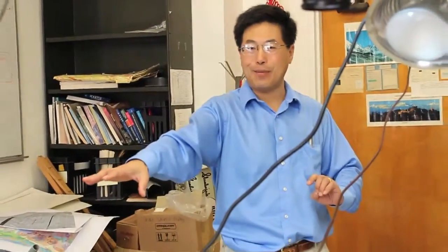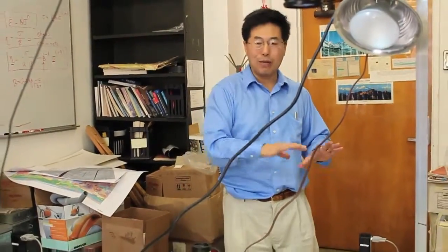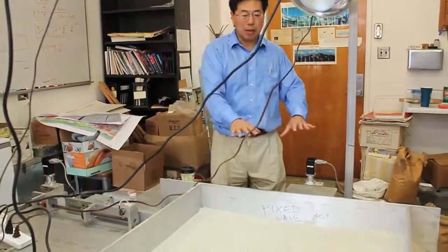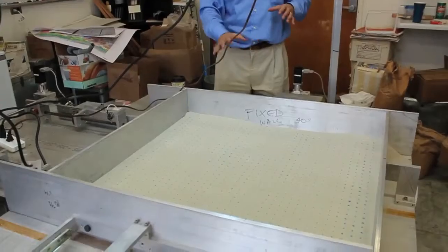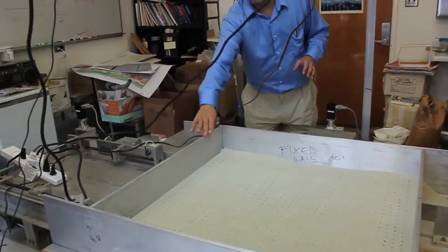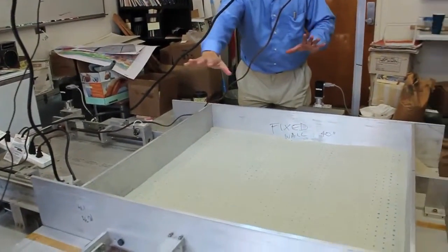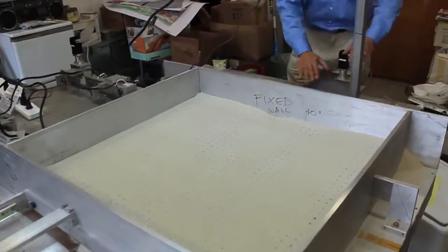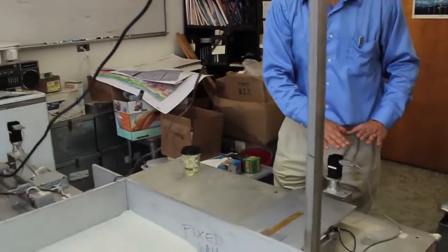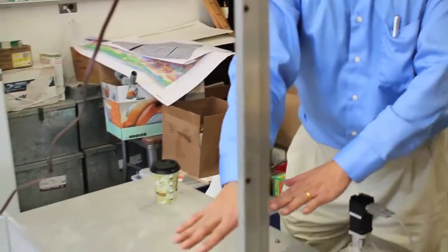And basically picking out each of those blue dots in a photograph, you can calculate or model the strain, or actually the velocity, which then you can turn into strain. Okay, so now we're running the experiment. Robin just gave the command from her command center computer, so everything's automated. So we can set up a speed, duration of the experiment. So right now we hold this boundary and that boundary fixed. So make it very simple. We only move one, which we call the basal shear or basal plate, which is driven by this step motor. It's moving underneath.